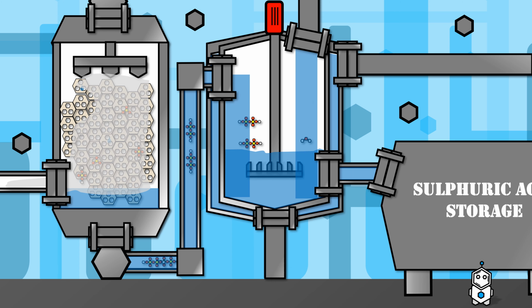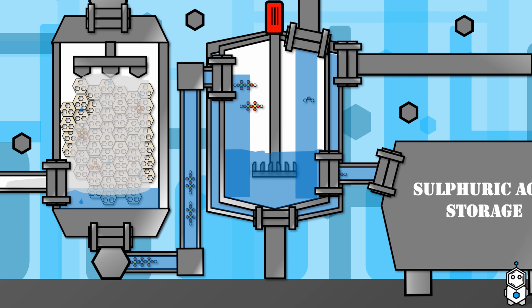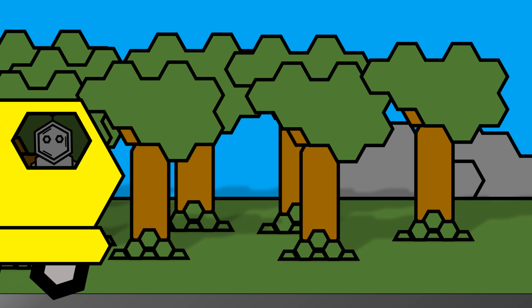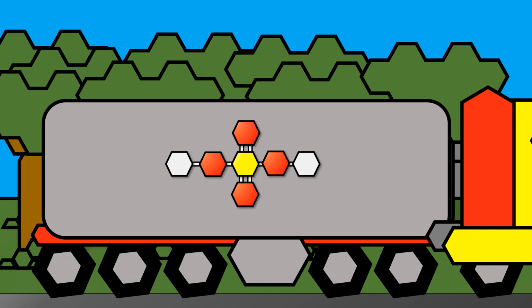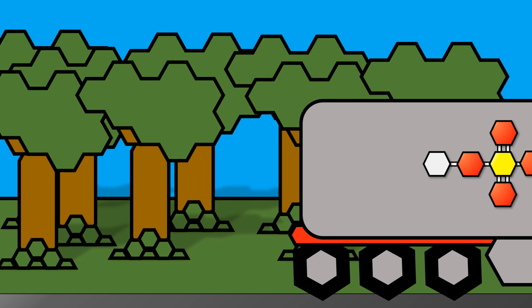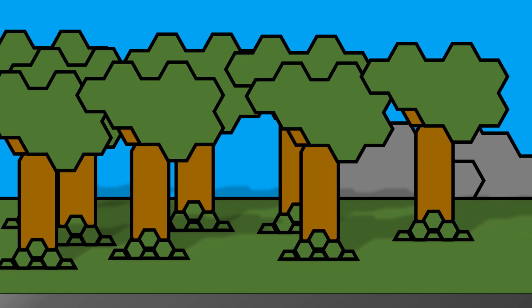The oleum is then pumped to a continuously stirred vessel to react with water to form sulphuric acid. Oleum reacts violently with water, releasing a lot of heat. Direct contact with water causes it to splatter, which is why it's carefully handled during the dilution process. The vessel is cooled with a chilled water cooling jacket to remove heat generated from the dilution. The sulphuric acid can now be shipped to other processing plants to be manufactured into all kinds of products. The Benzenes have now designed and built a process to produce a key intermediate chemical.